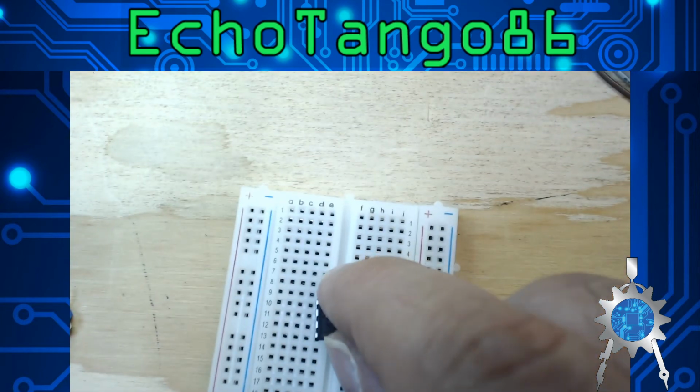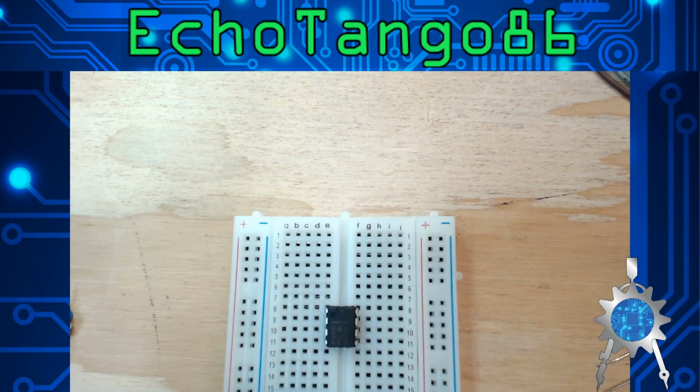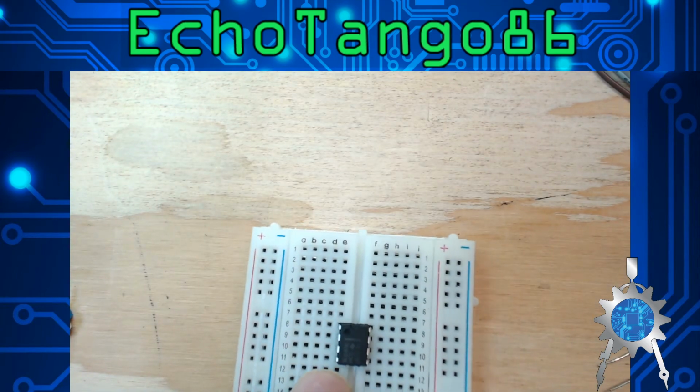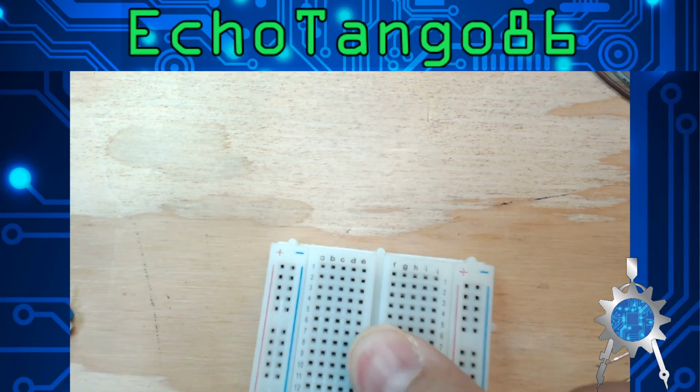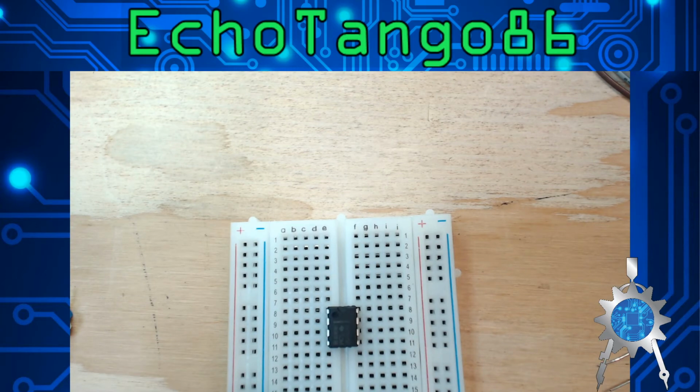So I would recommend putting it down right about there. Maybe have it go into pin 7 or 8 and the bottom go to 11. So 8, 11, that's a good spot for it right there. You have a nice connection to your ground. Looks a little cleaner. So pin 1. Pin 1 is your top pin here, up here, and that goes to ground, but in between the ground and your positive, which is pin 8, you want to have a capacitor there.